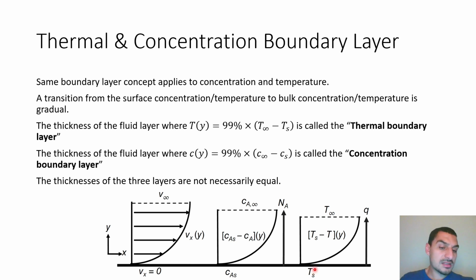This is kind of logical, and it's very similar to fluid mechanics. But there is a very important point here: you might have a system with simultaneous fluid flow, mass transfer and heat transfer. You have the three going on simultaneously, and in this case you can predict that you will have a boundary layer for each one of the transfer phenomena. But you have to keep in mind that there is nothing that dictates that the three boundary layers are equal. You might have different boundary layer thicknesses for the three transport phenomena for the same system.